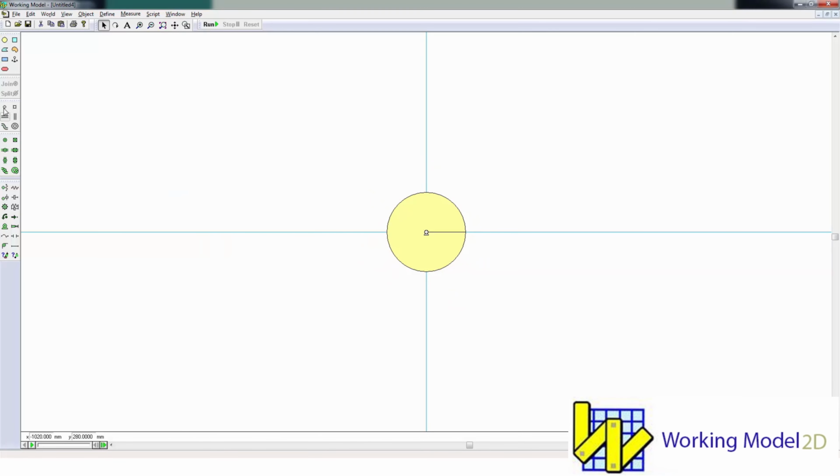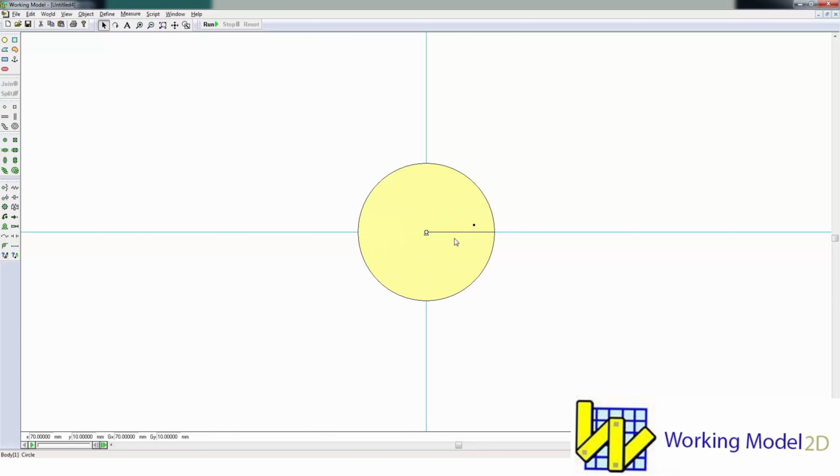Now we'll go ahead and add a point element onto the disk. If I move my cursor around the disk, I have these different snap points that'll wake up. On rectangles, I can use the midpoints and the endpoints and things like that. So here I'll just put it anywhere on the disk because I'm going to specify the coordinate positions for that point. Now, I have the point selected after I placed it there.